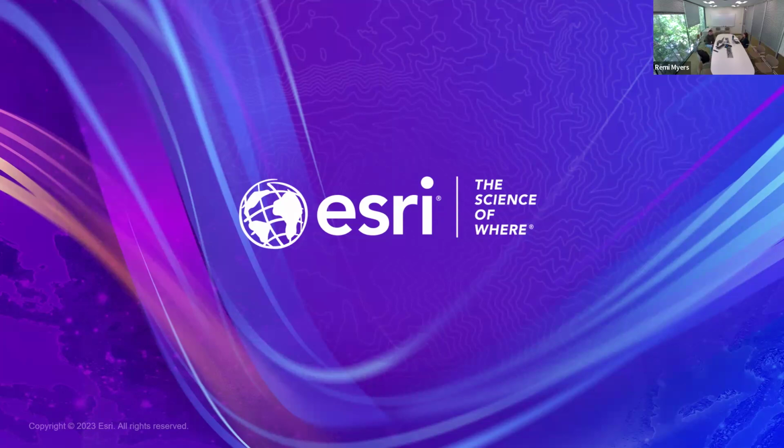The utility network uses a new type of versioning called branch versioning, and branch versioning is unique in that it never deletes your data. It goes into delete status. You don't see it on your map, but it's still exposed in the database. So as some of these larger utilities enable and disable, things like the dirty areas, even though they're deleted, can bloat or enlarge some of the database tables.